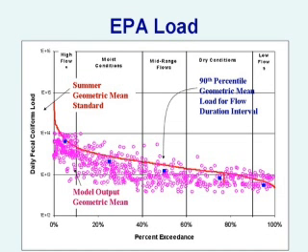We even took that same model output, and this plot shows the CSO loadings from the untreated portion of the collection system. The treated portion is way low, below 100 counts per 100 ml, but this is the untreated portion that once in a while bypasses the treatment facility. Instead, in this analysis for the frequency of excursions, we've looked at the outer envelope of the CSOs, and we've increased that to the pink line.